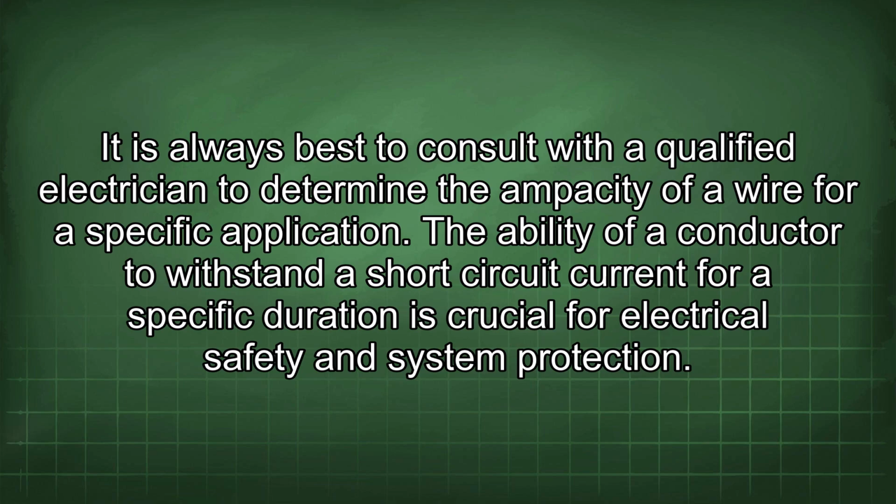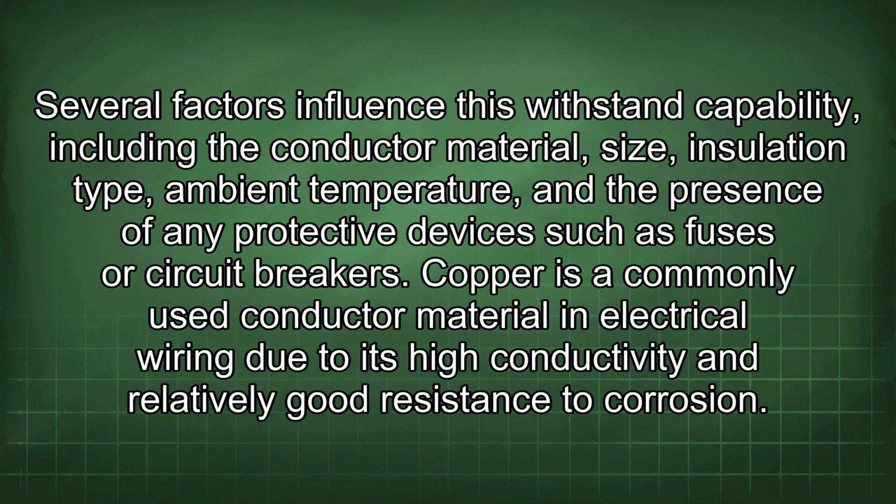specific application. The ability of a conductor to withstand a short-circuit current for a specific duration is crucial for electrical safety and system protection. Several factors influence this withstand capability, including the conductor material, size, insulation type, ambient temperature, and the presence of any protective devices such as fuses or circuit breakers.